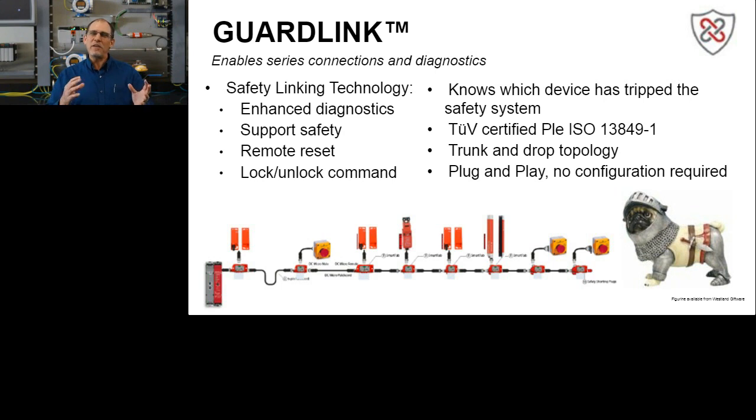And so one of the things you can do is as simple as looking at how many times the e-stop is pushed on a particular shift. You can figure out, hey, this operator doesn't understand there's a controlled shutdown and there's an e-stop. You do training, and guess what? Your customer's production line gets more efficient.